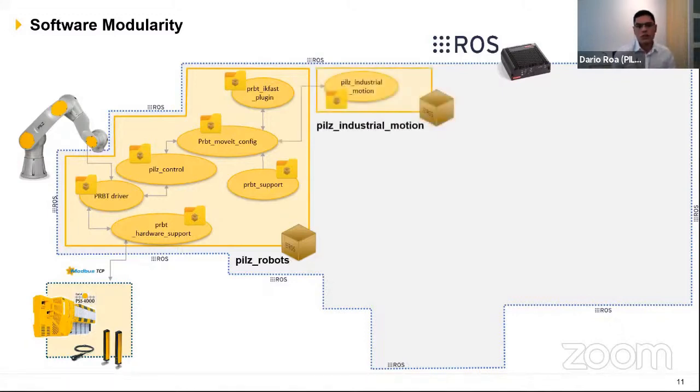This is where we'll start our work, using the Pilz Industrial Motion package, which, as you may know, is now being used by many robots, and I'm very happy to see that in the wild. It is the deterministic package for motion control with the robot. This gives us the robustness of your typical PTP, LIN commands that you're used to with industrial robots. Now you can have it within ROS.